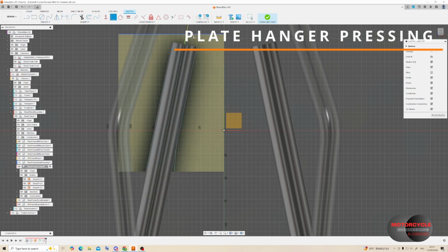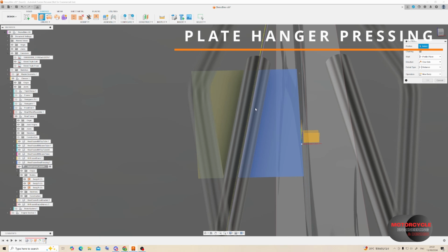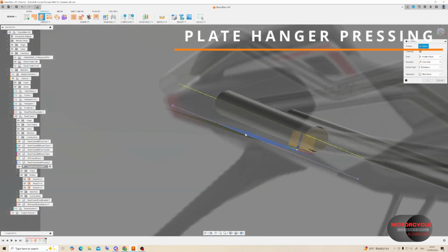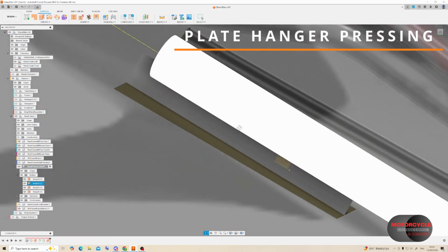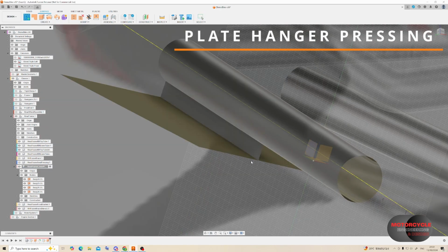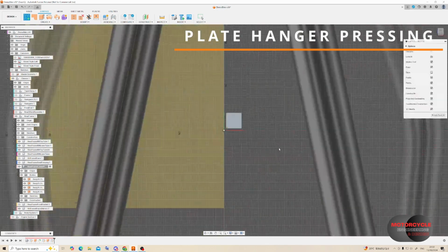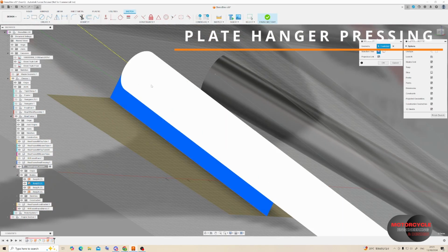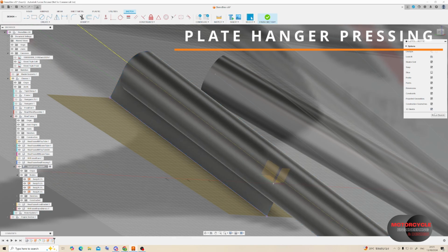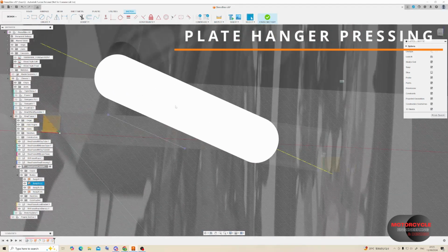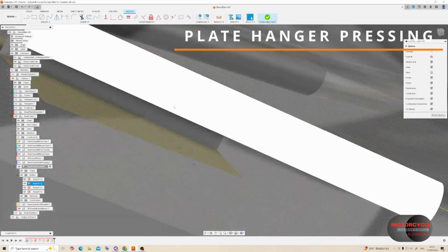So I decided that I want to have a swept surface which will be parallel to this tube, and in order to do that I want to extrude a surface straight into the tube and then use a trim to create a curve. Now it doesn't actually matter to me which part of this surface remains, because I only need the curve for reference.